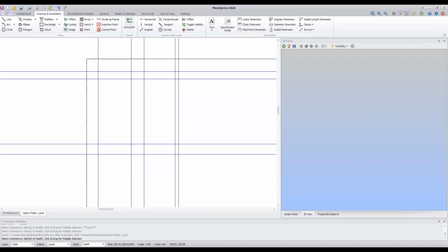So if you've laid out construction lines as we have, you're ready to start drawing the footprint of your design, and it's actually a really simple process. So in this particular exercise, you'll learn how to select a type and specification of external wall, how to input your foundation details, your wall height, and so on, and how to draw the walls by clicking on the intersection points on the construction lines that we've already drawn.